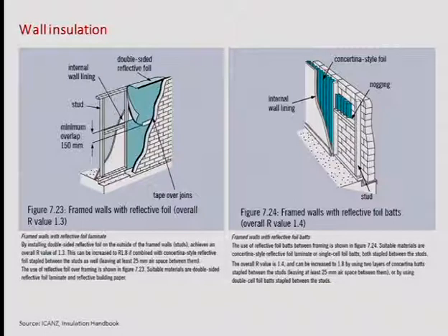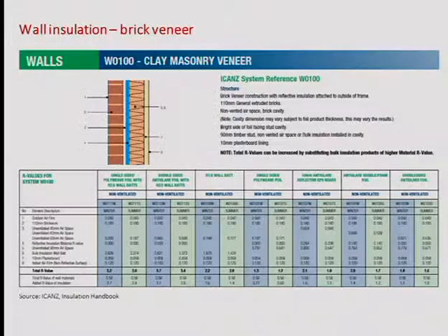And you see here some details in axonometric views which are more understandable on how to place. You see the stud walls, and then the insulation, the reflective foil, the protection, and then the external layer. So there are several images in axonometric views and perspective view that will probably help you to understand in 3 dimensions how the element works. They also provide thermal and acoustic data. So they tell you exactly how a specific section performs.